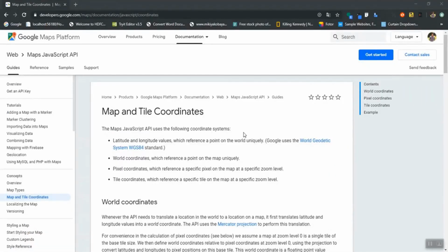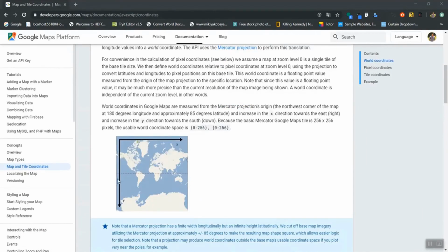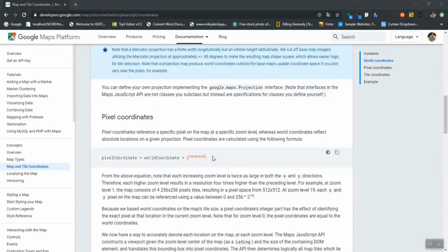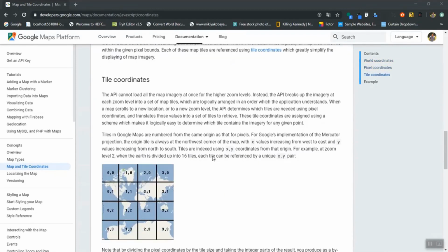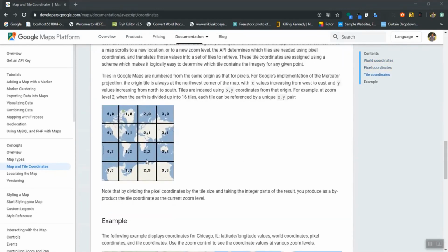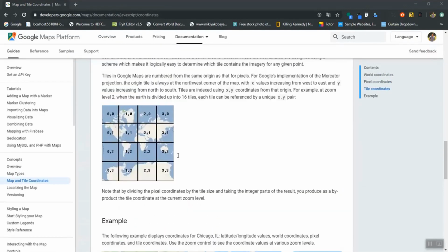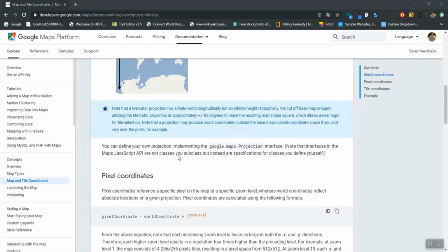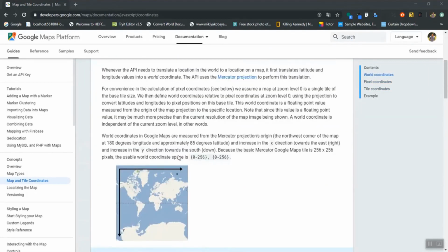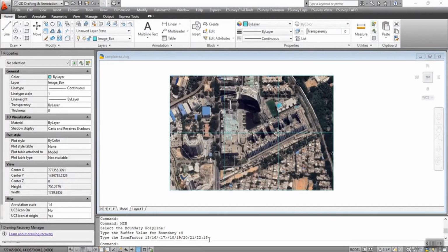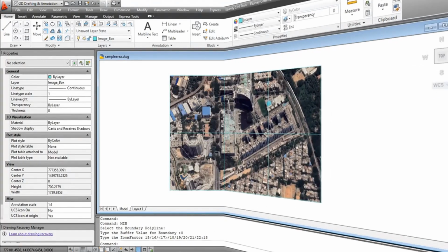You can download Google Earth images of different resolutions. At zoom level 1, a 640 x 640 size image fits the whole world map. At zoom level 2, 4 images make the world map. Similarly, at higher zoom levels, you get better resolution images. Depending on your project requirement, you may download the images. Most of our users download images at zoom level 18 and 19. At zoom level 18, one image is 275 meters by 275 meters.